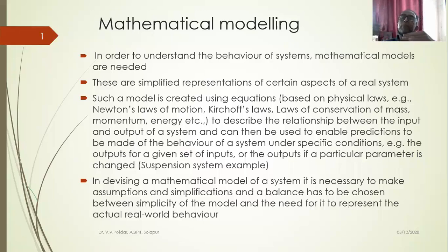Now when I say that this mu is changing with respect to time, what does it mean? Mu is maybe increasing. So what is happening? Mu is equal to tau upon dou u by dou y. So when mu is increasing, tau will increase. So the resistive shear stress that I am applying, I need to develop more shear stress. So I need to apply more tangential force.